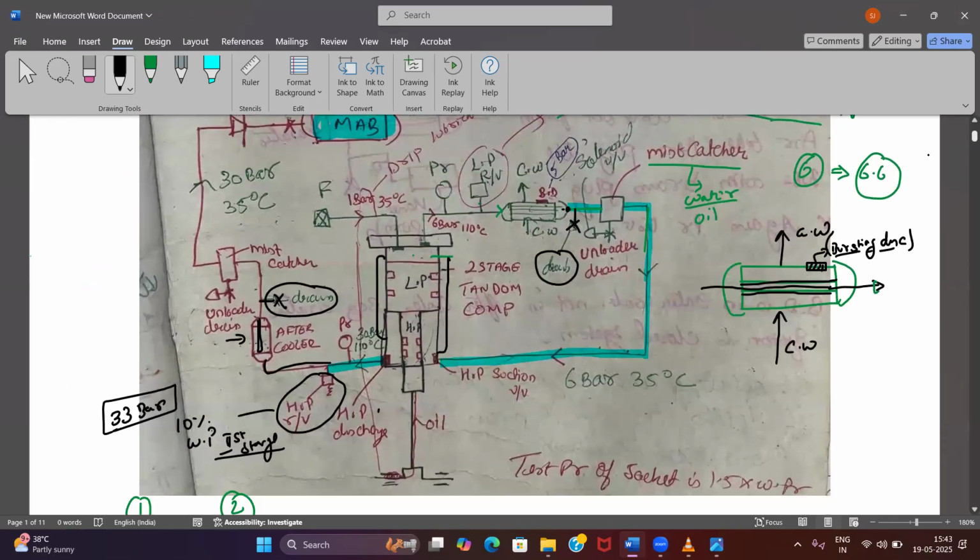All this water will fall in your engine room, wherever your compressors are installed. The compressor, sir, it will spray water everywhere. Suppose in the same scenario, suppose we install the wrong bursting disc, one for a higher pressure. What will the indications be, sir? Suppose the air tube is somewhere leaking, something is going to break.